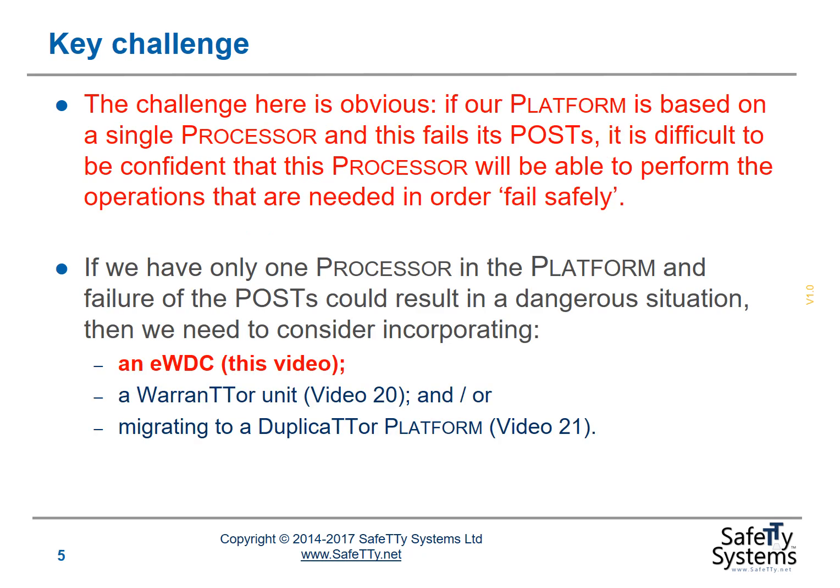The challenge that we've discussed in previous videos is obvious. If our platform is based on a single processor, and this processor fails its power-on self-tests, it's difficult to be confident that this processor will be able to perform the operations that are needed in order to fail safely.